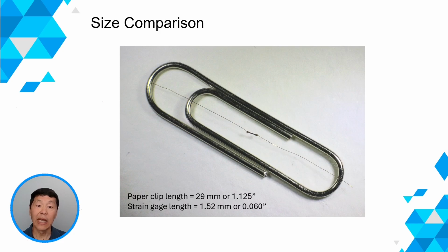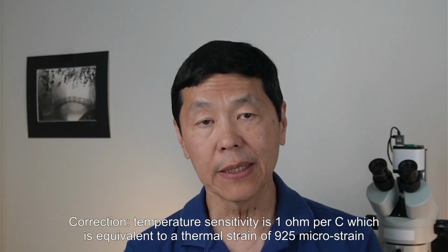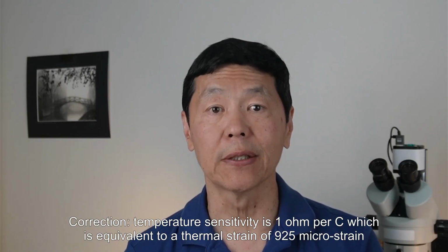The small size of the gauge is great if it can be bonded to a sensing element in a reliable way. It requires, however, a lot of manual skill to handle it without breaking it. We'll go over in a future video how to bond this strain gauge and how to solder the gold wires without melting them. A major inconvenience when working with semiconductor strain gauges is how to handle their high temperature sensitivity. For example, a semiconductor strain gauge can change 7 ohms per degree Celsius.